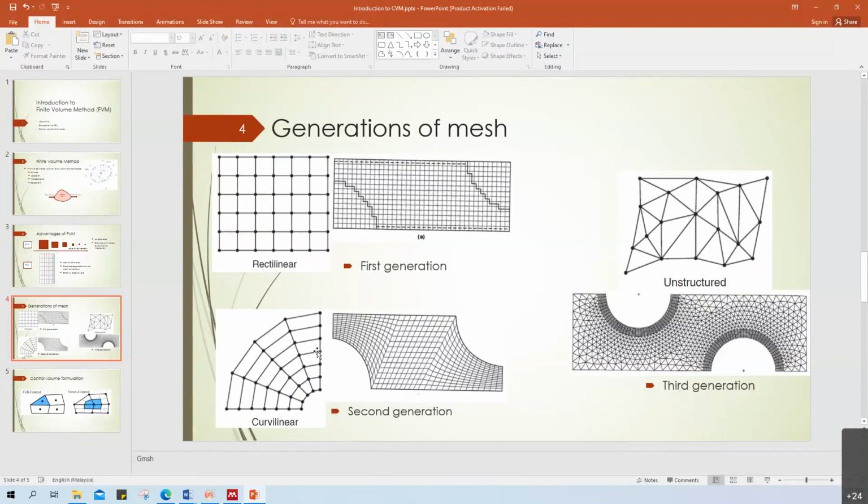For this type of mesh, if I'm not mistaken, you have to define at least four lines: the first one, second, third, and the fourth one. For curvilinear mesh, you need to define your boundary first, because the mesh is dependent on the boundary. For the others it is actually quite easy. You just pick the type of mesh, pick the control volume you want, and apply the mesh.